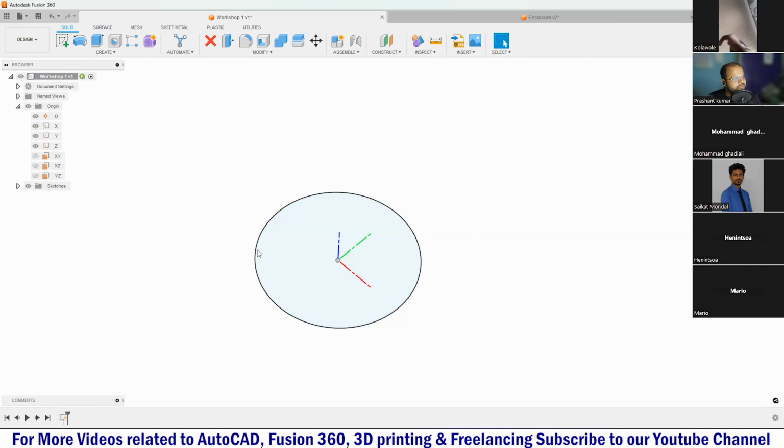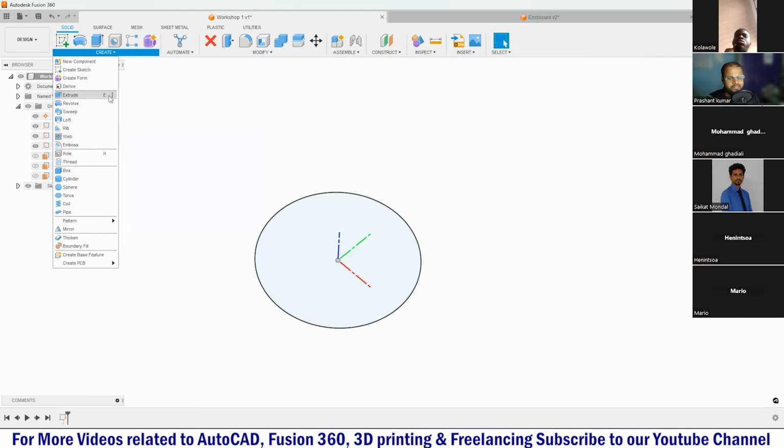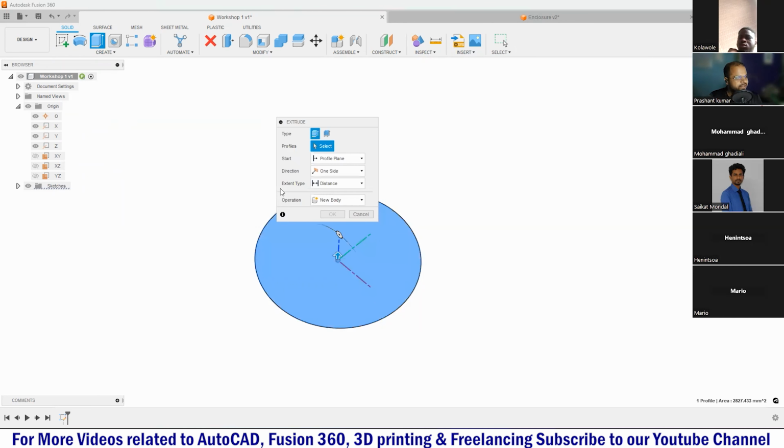So the first thing that I want to do is convert this to a 3D model. For that, we are going to explore the tool inside the create panel, and that tool is called the extrude tool. Here you can see in front of a few of the tools there are letters given, like in front of the extrude tool there is a letter shortcut given, called E. That is basically a shortcut. If you don't want to go inside your tool panel and activate your tool by clicking over here, you can also activate it using keyboard keys, right? If you just press E, here you can see the extrude tool got activated. So you can also do it this way.